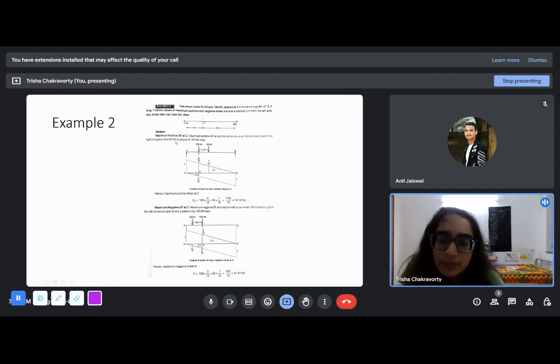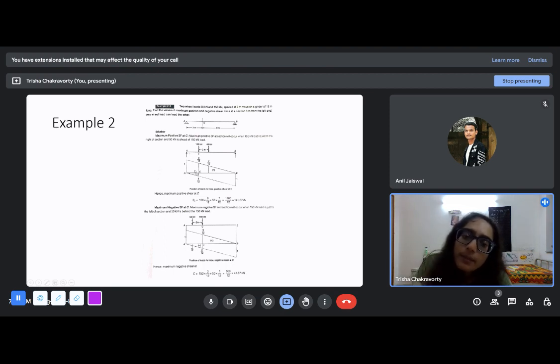So see, for the maximum, firstly you have the ILD at C. You have the influence diagram of the shear force. It will look like this. Here A is 3 meters and L is 12 meters, so the ILD will look like this. This is 3 by 12. It has a jump, and from 9 by 12 it reduces to 1. And now I need the maximum positive shear force at C. Maximum, you see, now this ordinate is the maximum.